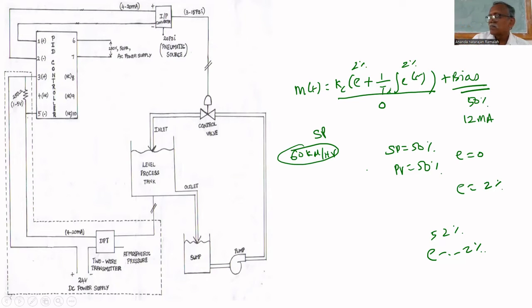You cannot put the controller in action at ground level. Once it reaches 900 kilometers per hour and the correct direction, then you can put it in autopilot mode so that the controller will adjust if any changes occur. If air density changes, speed will change. If altitude changes, speed will change. So, if speed is changed, the controller will take necessary action. Bias value, the pilot has to find.